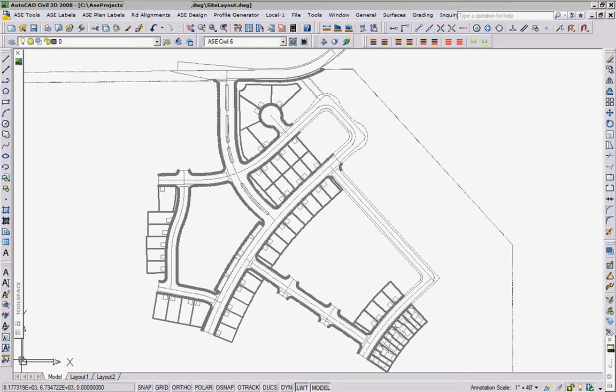There are two ways to define alignments in the ASC, either automatically or manually. If you choose to use the automatic option, you will have to specify which layers ASC should use for those centerline definitions. Also keep in mind that ASC only needs centerline definitions and not offsets. The base map control completely handles the offset alignments.